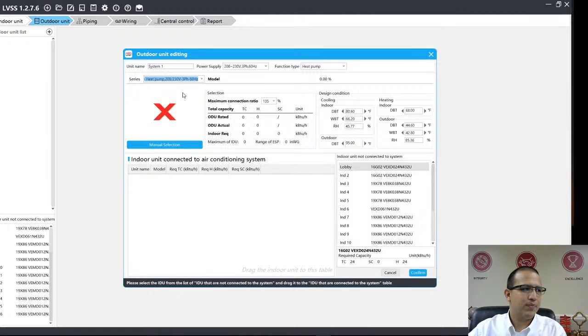I'm gonna show you the slim. It looks like a mini VRF. We go up to 10 tons: 6, 8, and 10 tons, and it's a much more affordable unit than the regular top discharge model. So that's for projects where you need a more economic option for your customer. They're actually easier to install. They are easier to service. So that's an option for some projects.